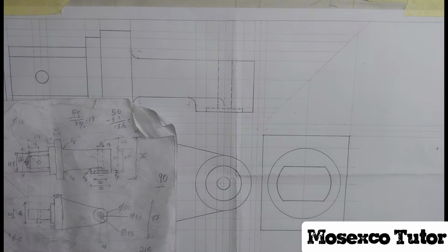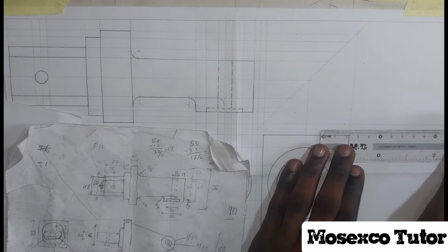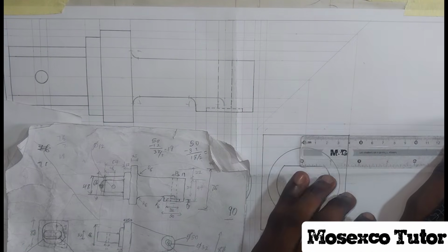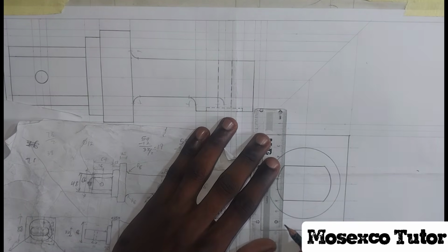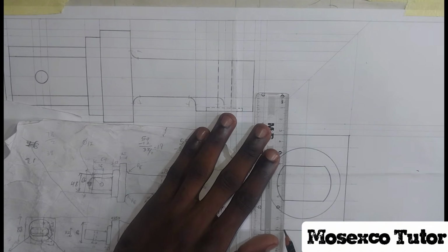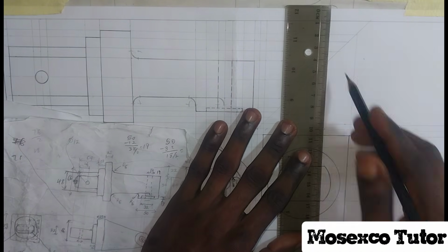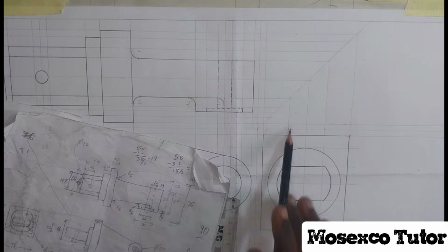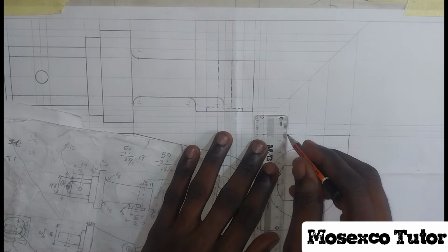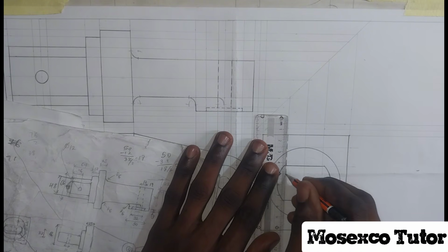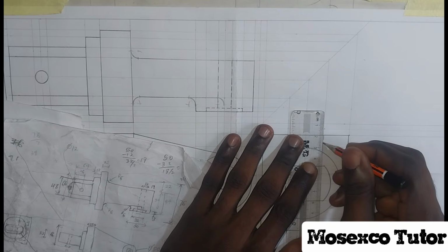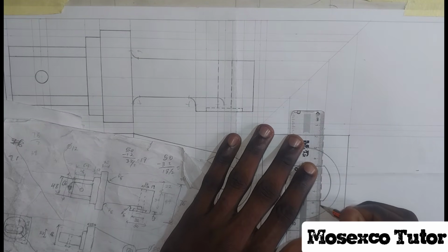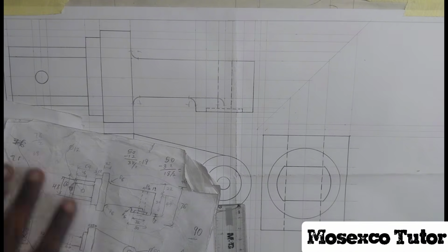Now I started with this other side of the plan. That's 2.2. I marked 2.2 and 3.2. I join together as a faint line and I extend it upwards. As you can see there, it will intersect with the one that comes from the plan, and also that one. So 2.2, then 3.2, that's what I did. But in between now, it will be a thick broken line, not a continuous line, to indicate that that part cannot be seen, but it is there. So thick broken line for those two vertical lines there.